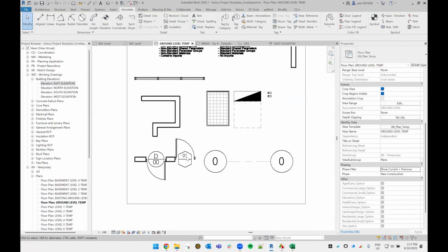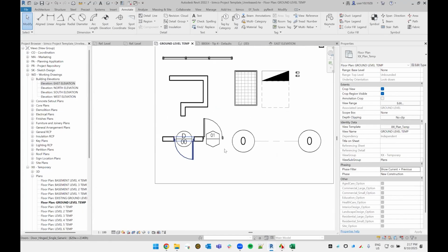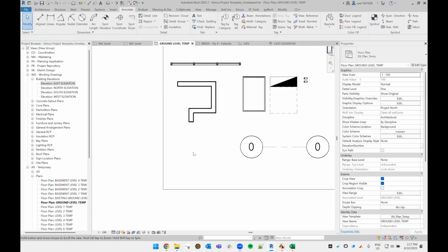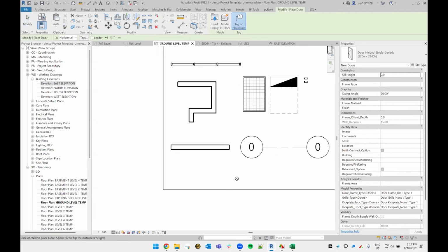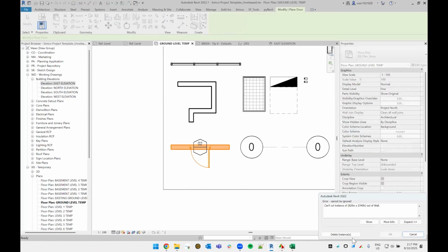Last change on any mark value for any element will be the start of the next sequence. So, okay, we've put in 2 doors here. We've played around, we've tested, we've deleted them. Let's put in a new wall. Now let's put in a new door. Okay, someone's about to start a new project, right? They put in their first door. It's door 2. All right.